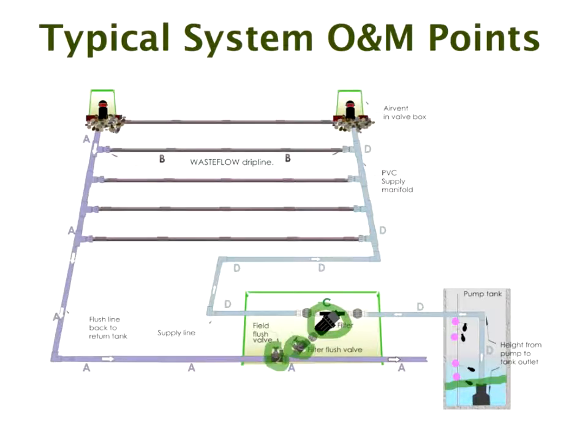Then you've got your air vacuum relief valves up here. You can screw off the top of these air vacuum relief valves and clean them out. Make sure that the ball is floating up and down freely. You do get insects, often spiders, that seem to like to crawl inside there and build their nests. That seems to be quite a frequent problem. And then, of course, they stop the valve from seating properly and you get leakage. So those need to be cleaned every 6 months.